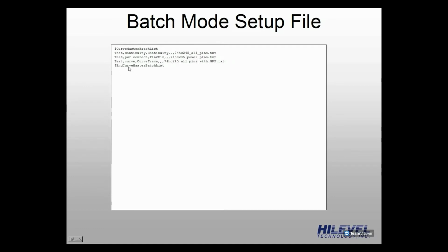One very important point is that the path to your files here is relative. The batch mode setup file and all of your supporting files must be in the same folder. So when you want to move the test to another folder, be sure to include all of the files needed.